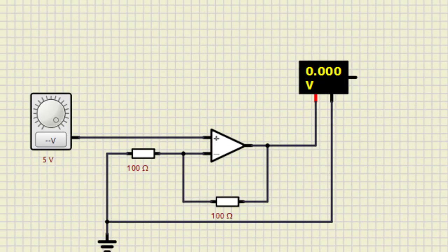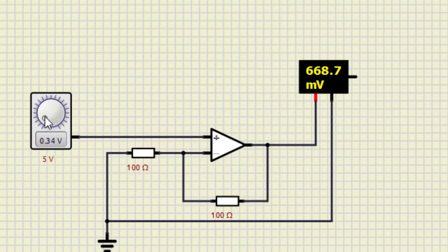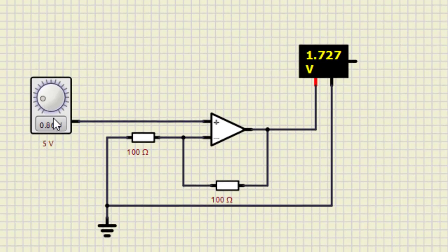Now let us turn it on. So now we have turned it on, and we can also turn on the power supply. We are starting from 0, so let us start it. So this is the input. Now this circuit is turned on. Let us make this input 1 volt. So we just move this dial. Now this is around 1 volt. So this is 1, and we are getting 1.996, which is almost equal to 2 volts. So input is 1, output is 2. Now if we make the input 2, we must get 4, of course.